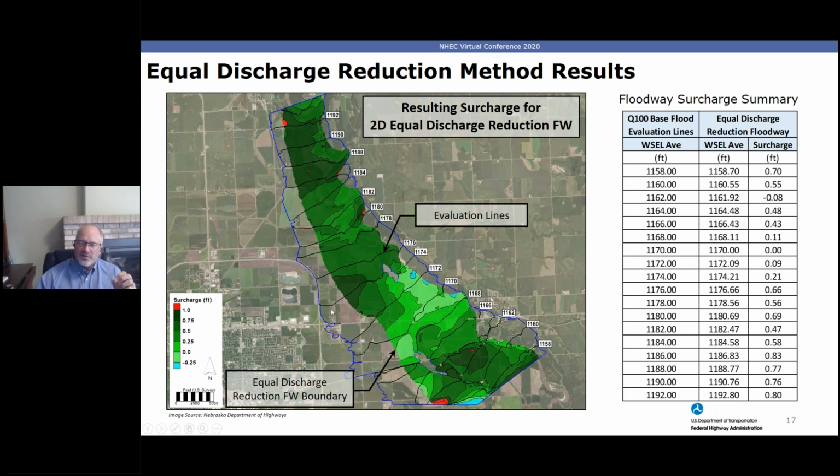All right, so now if you've done floodway analyses in 1D modeling, you know that when you set the target of 1 foot, you don't automatically get a 1 foot rise everywhere. Okay, and so the same thing holds true in this method. It's a target, all right? So it goes through each cross section, makes some approximations, and delineates that floodway. You run it and check the result.